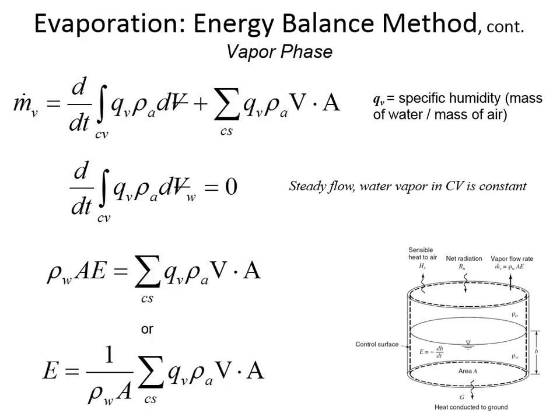How quickly water can evaporate is partly a function of wind conditions, because on a very windy day, that layer is a lot shorter so that the dry air is closer to the water. If the dry air is far away from the water and you've just got this fully humid layer of air above the water, then the evaporation rate is going to be limited by transport.